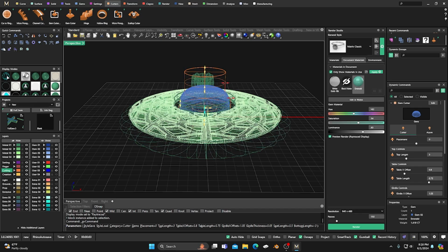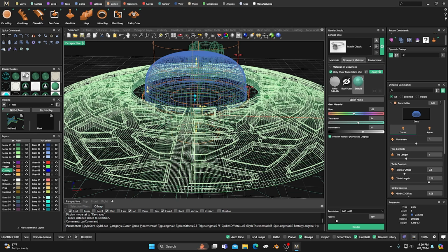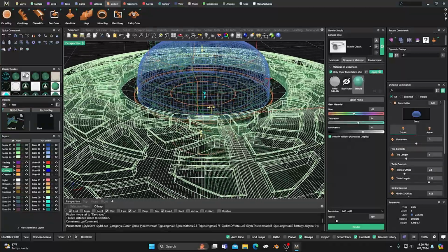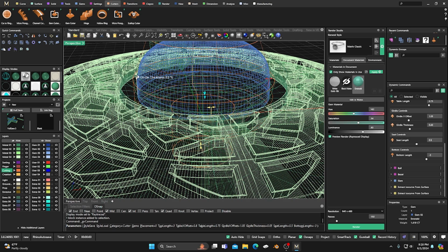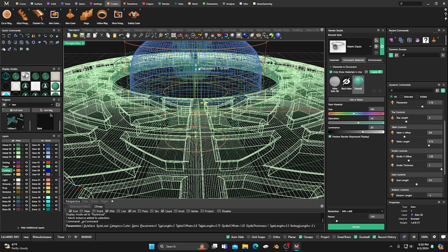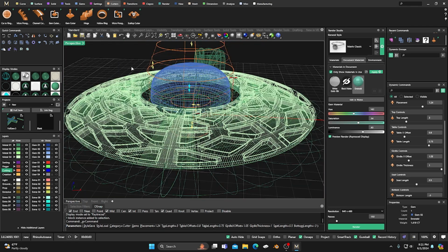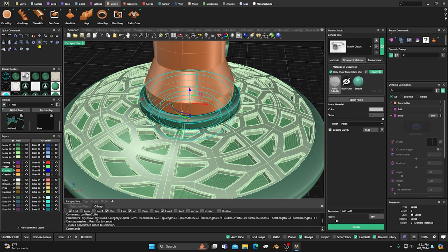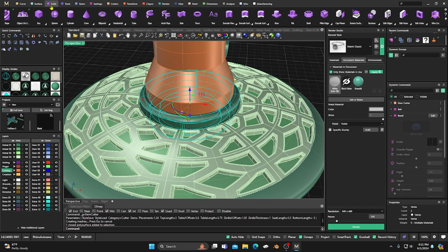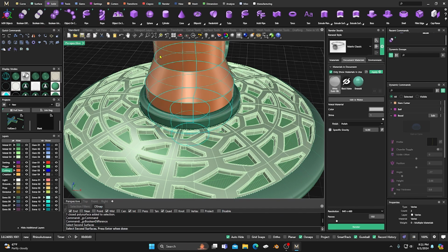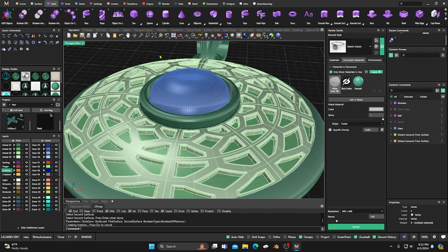So let's go to wireframe and see what we got going on here. It looks like it's going around it all. But we'll need to make our girdle thickness much thicker, and our placement, we'll drag that up so that it'll cut all that out, right? And let's give it some shading so we can't see any of that. So let's go here, go to our solids, and we'll do a Boolean difference. That's our first surface. Our second surface is our cutter, enter, and then enter, right?